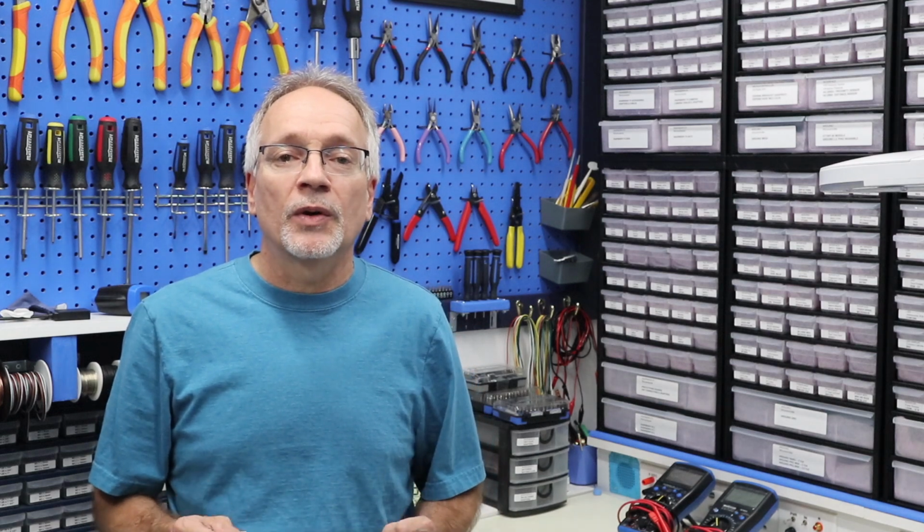A lot of people also simply use DuPont pins, and even in that case, there's no standard as to what the pinout is. I have a number of I2C modules, and they have the same 4 pins, but they're not necessarily in the same order. Another thing about the I2C bus that varies is the voltage levels that we can use. Now the two most common levels are 5 volts and 3.3 volts. Most of these discrepancies are things that we can get around quite easily.